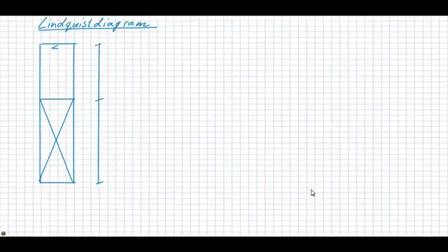When we consider a filter with a filter bed height of 1.5 meter and a supernatant water level of 1 meter above the filter bed, and there is no flow through the filter, then we can draw the hydrostatic pressure line.